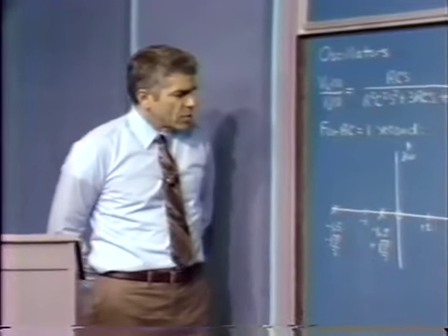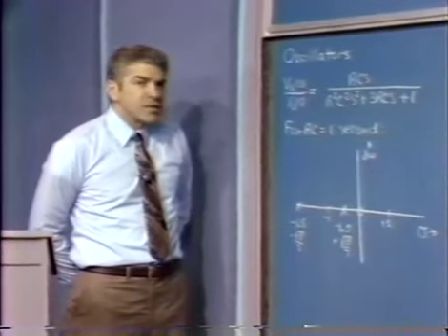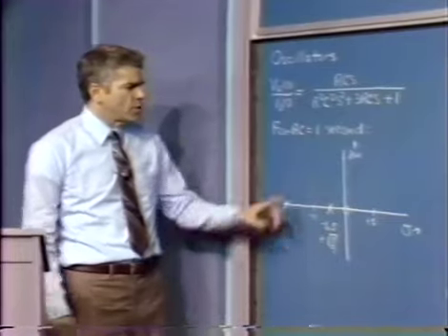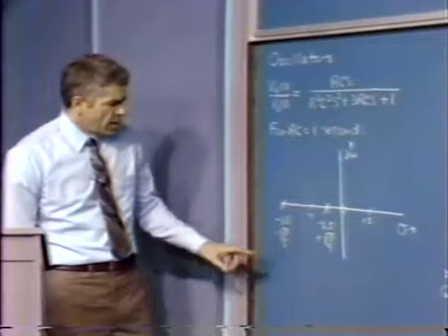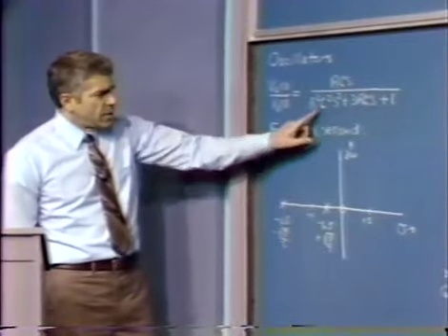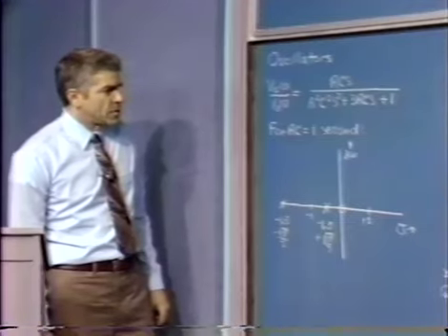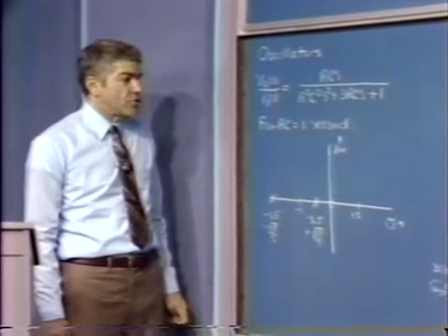We can see the effect of this by drawing a root locus diagram. Let me stress the fact that this is a positive feedback system. I've also normalized things to RC equals 1 second. If we factor the denominator of the Wien bridge transfer function, of course all of the frequency-dependent elements are concentrated in the Wien bridge. I've assumed the operational amplifier has negligible dynamics.